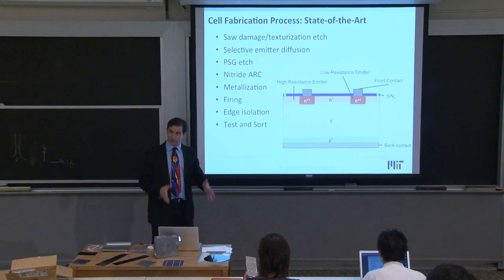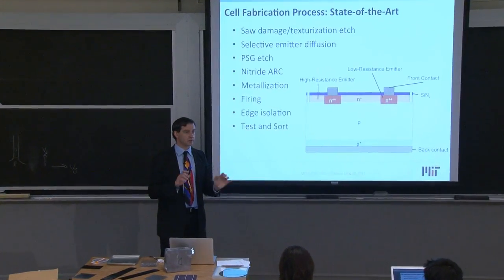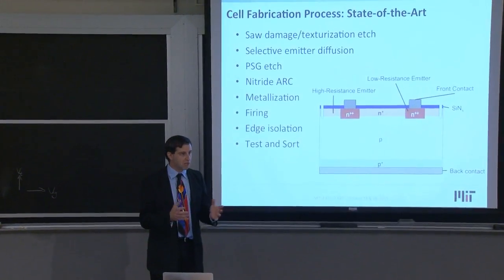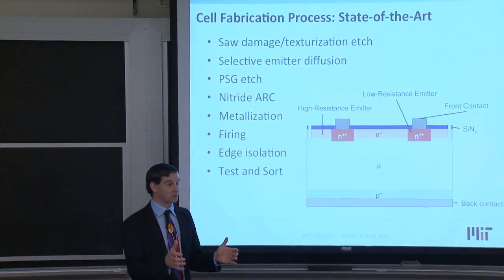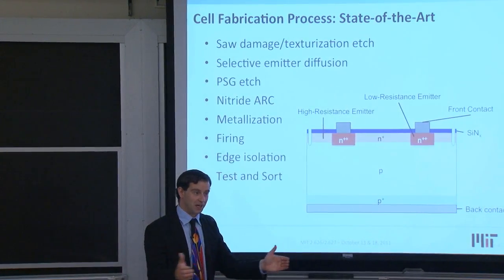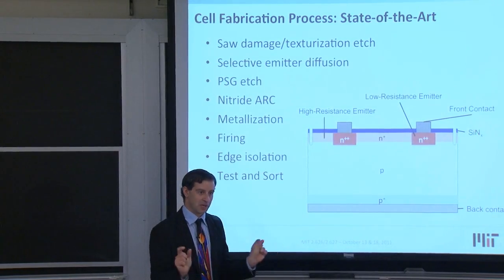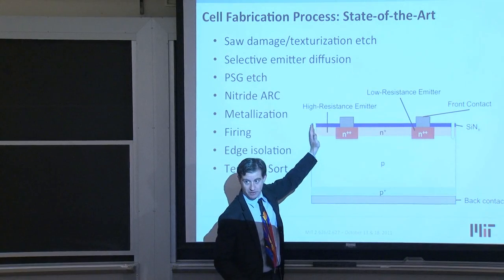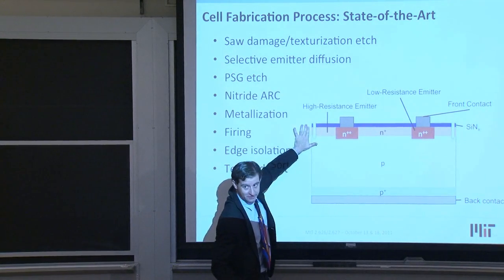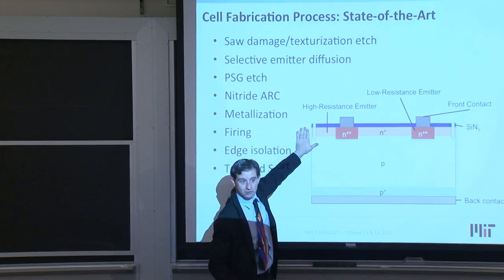Because you know your solar cell has a certain current density, let's say, milliamps per square centimeter. But if your area, your square centimeters, is smaller because you're cutting too far away from the edge, you're throwing away good material. This isn't a trench all the way through. It's just electrical isolation. So essentially, this material over here still exists. It's still hanging on to the device, but it's electrically isolated.